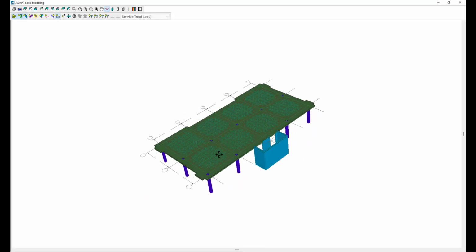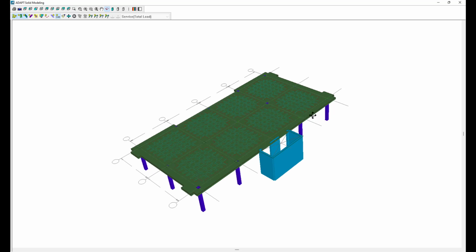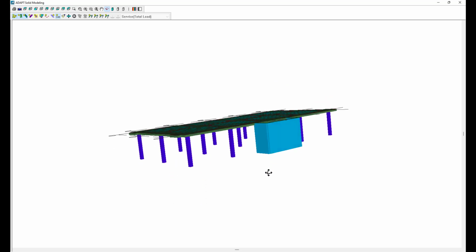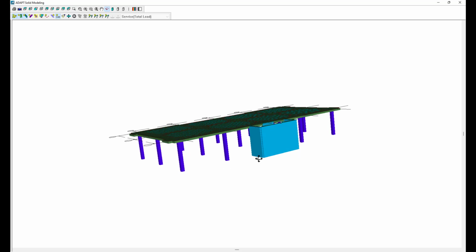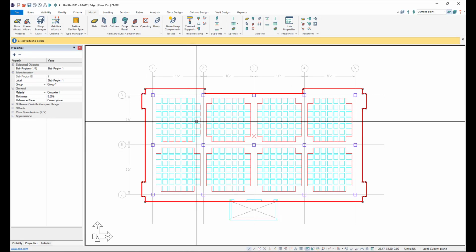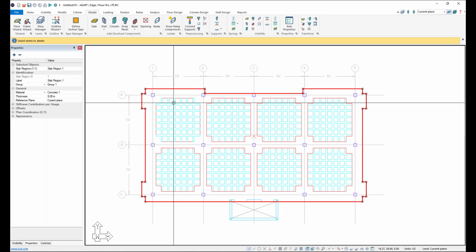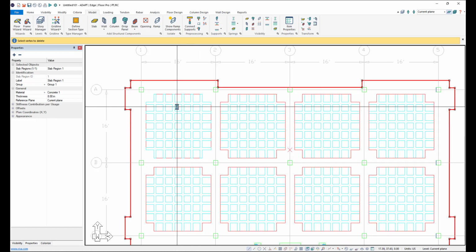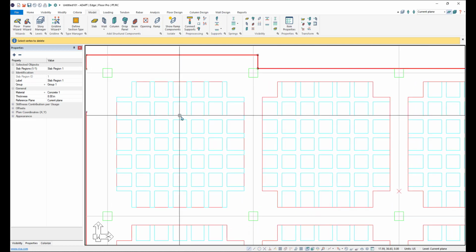And so you see the CAD drawing overlapped with the model elements, but you can see the modeled elements so far, the columns and walls. So now we need to go ahead and model these bays of joists here. So I'm going to model one and then I'll copy it over. So let's zoom in here.